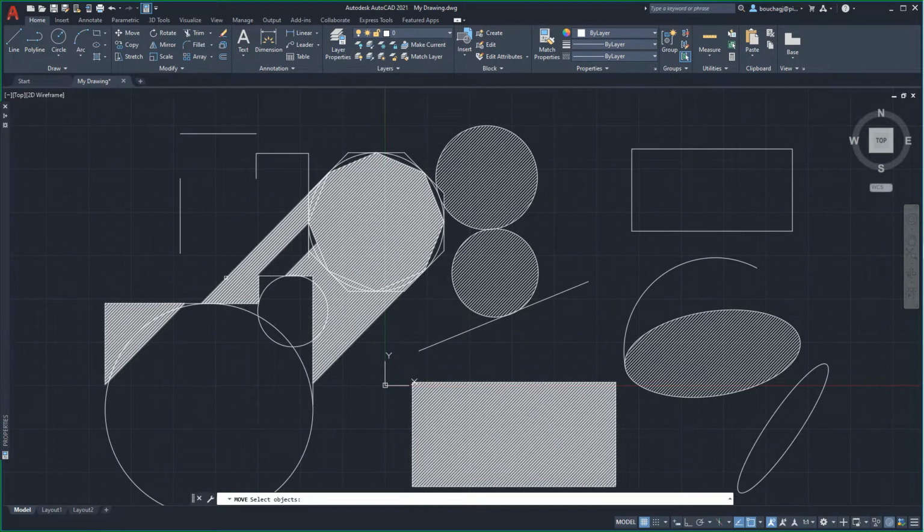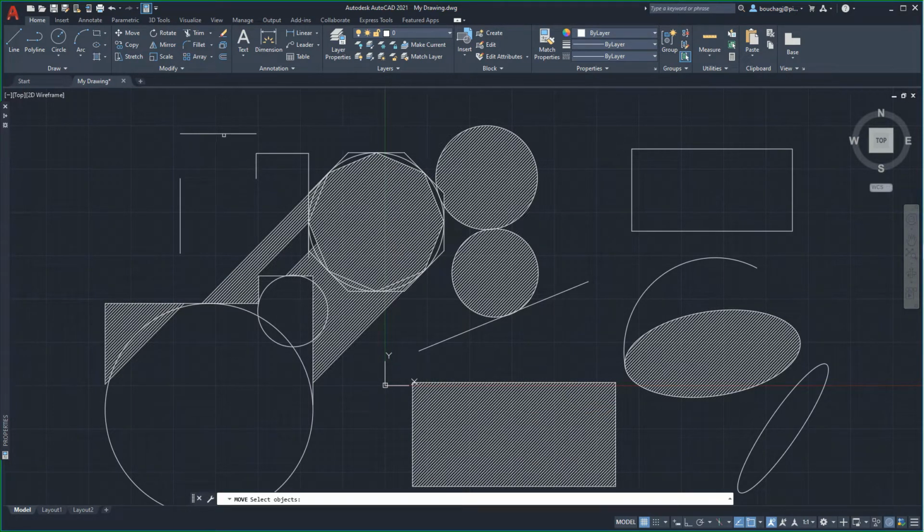Let's select this line segment we relocated in a previous video. The command history states "one found," confirming the selection of the chosen line. This history feedback is important and helpful to the user. Should the number of objects found be different than intended, the user has an opportunity to make any necessary additional selections or removal of objects from the selection set.